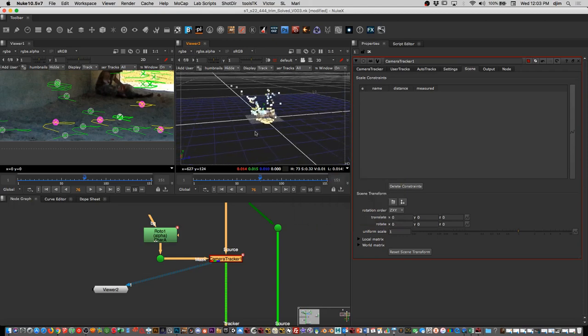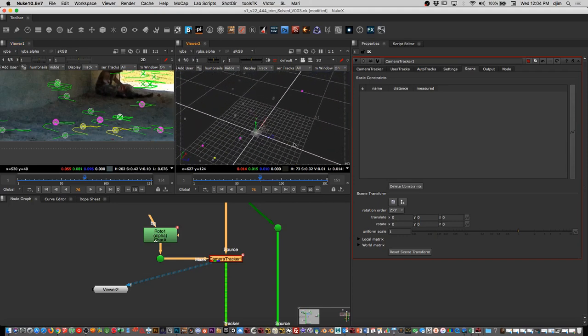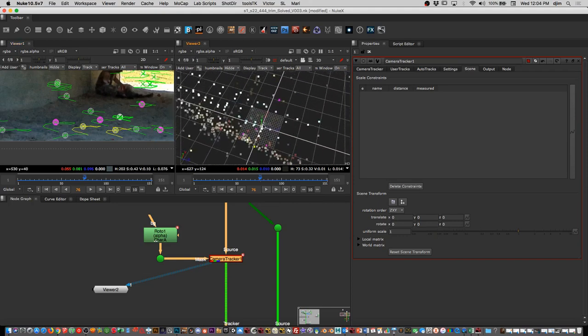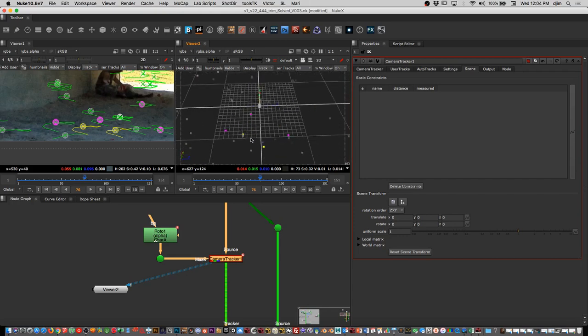For that, let's start by setting up the distance constraint, in this case, the scale of the scene. It's the same as in SynthEyes. You pick one, pick the other. So the same idea here. I'm going to pick 2 of these trackers, 1 and 2, and look at them to see if they're in an area that I want to establish as a constraint. I want the distance from that tracker to that tracker to be 1 centimeter in this case. If you actually measure it on set, you want whatever the set says. So if it's 1 foot, 1 foot, and so on and so forth.